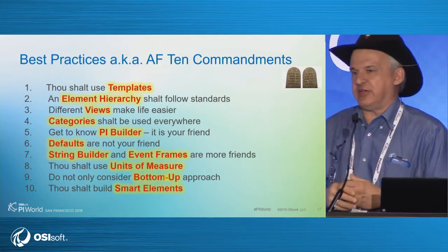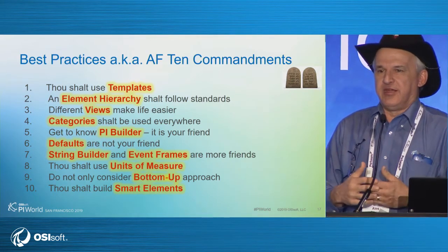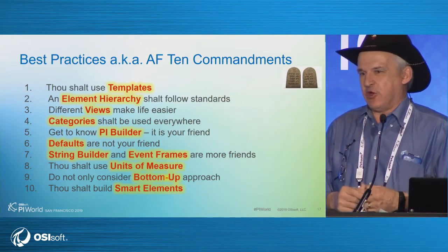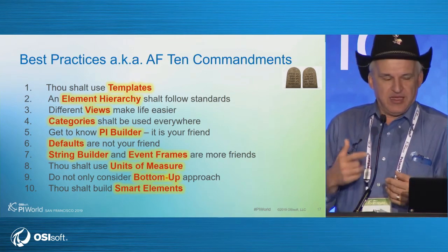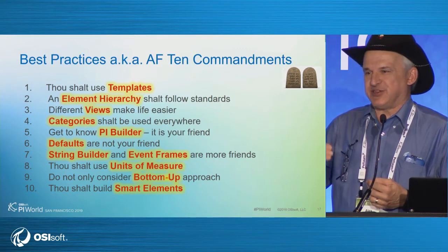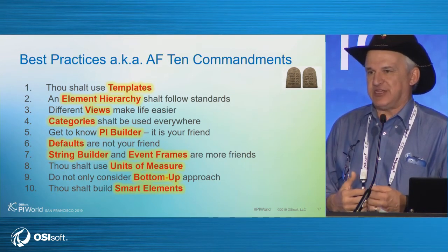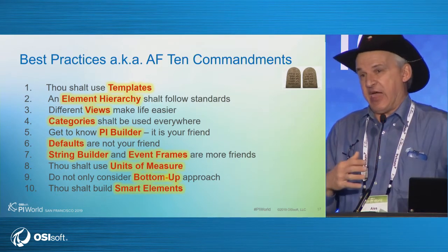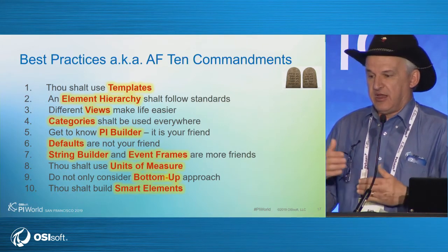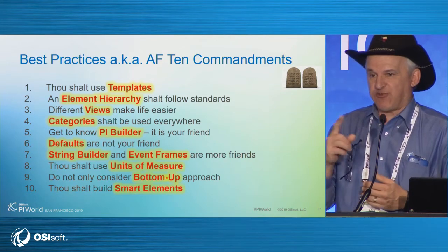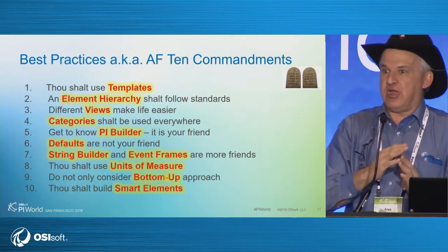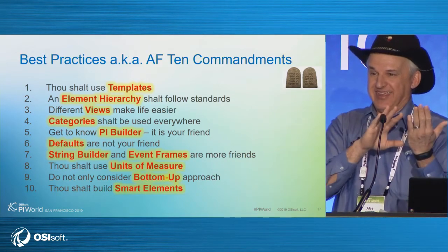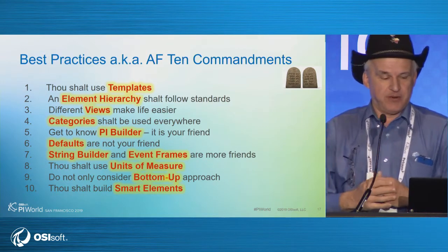Right? Dashboard using your measure. So those of you from the old Pi tag world, we had engineering units, but they were basically totally useless because nobody used them, or they used 50 different versions for the same unit. So it became not very useful. In AF, when you assign an attribute a unit of measure, that value now is not just a number, it's a value with a unit, which means I can easily convert to other units. And now we've added some stuff in AF in 2018 last year, where you can do class of units. So I can switch from my own English to the new metric, and I have these classes in the units of measure that let me switch all of the things from one base unit to other base units, one by one.